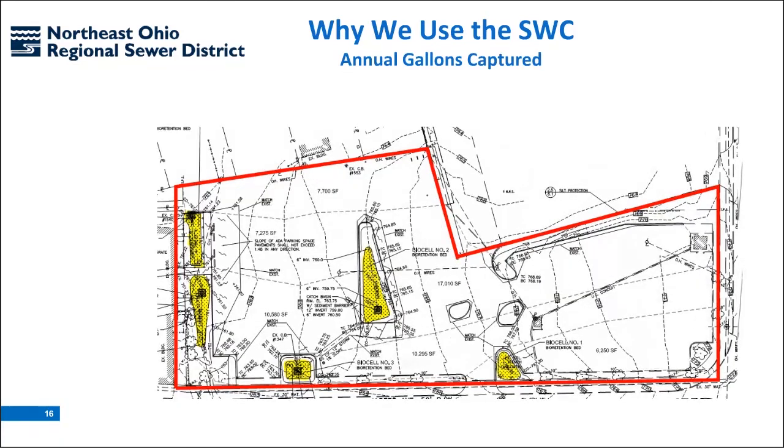And the applications typically show us the retrofit of the features of the property. In this case, they added 5 bioretention cells, maintaining the existing drainage patterns, but reconfiguring the parking bays on the property as well. Now we were able to capture the entire parking lot runoff and route it to a green infrastructure practice. And that represents a very typical project that we see through this grant. This parking lot was about 2.5 acres in size.